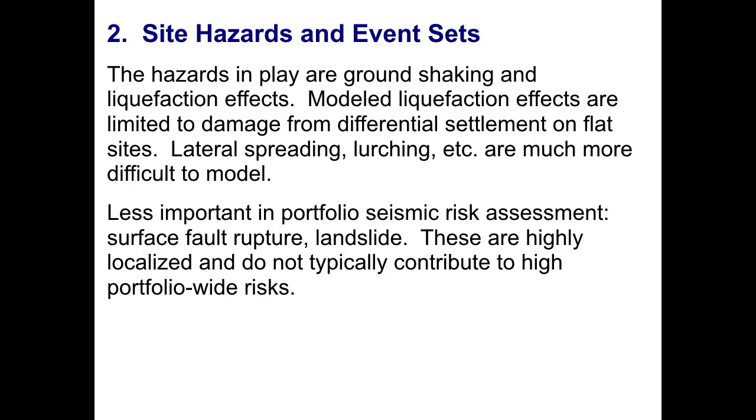Less important in portfolio seismic risk assessment are surface fault rupture and landslide. These may cause a lot of damage to individual buildings, but they're highly localized and typically do not contribute to high portfolio-wide losses, at least in portfolios where we have a large number of sites.